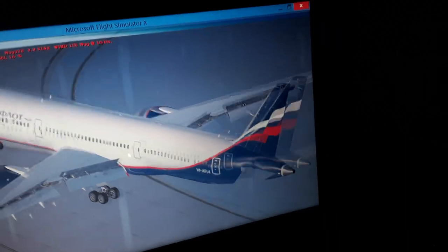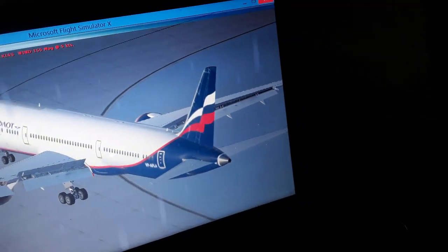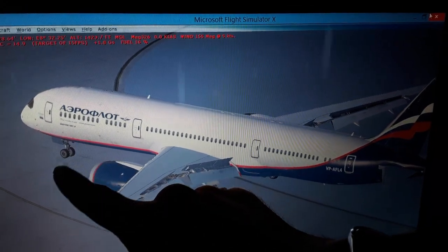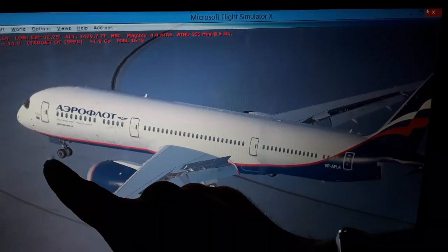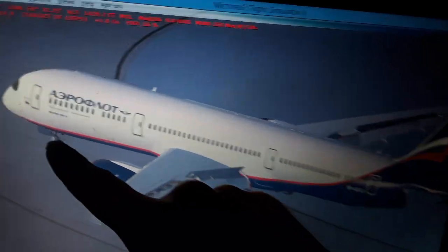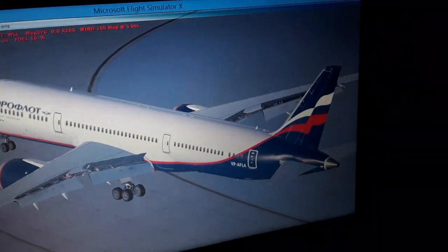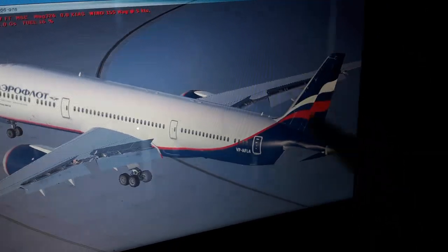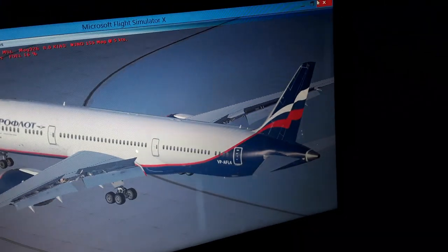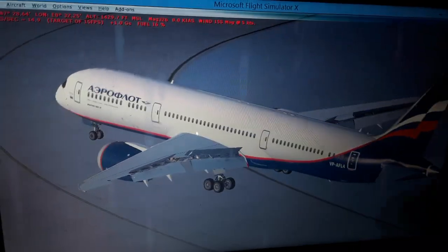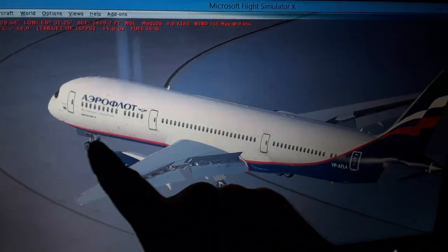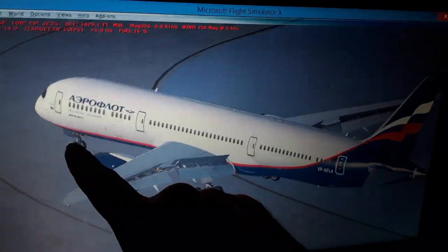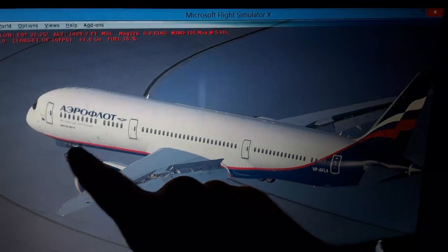The rudder becomes aerodynamically effective. So from 0 knots up to 45 knots, the nose wheel is deflected by the computer automatically up to 76 degrees, either left and right, for directional control alongside the rudder. Also, as we increase the airspeed above 45 knots or 72 kilometers an hour, where the rudder becomes aerodynamically effective, the nose wheel deflection is decreased by the computer automatically. You don't need to do anything, from 76 degrees to like 7.6 degrees.